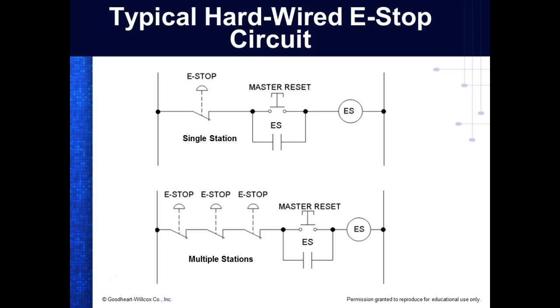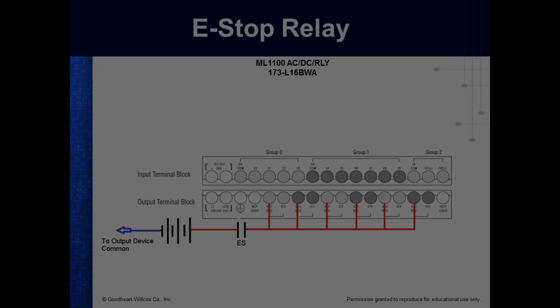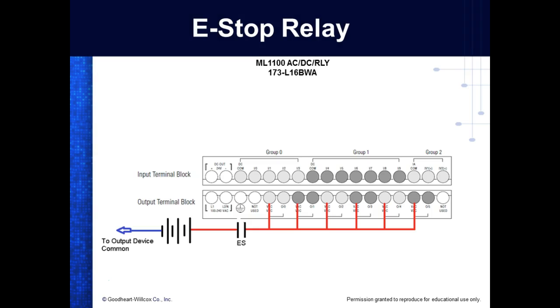Well, usually lines are divided into sections. Each section has a function in that line, and usually every section would have an e-stop button or an e-stop cord. A lot of these big production lines have cords hanging from the roof that you have to do what? You have to pull. So this is the standard e-stop circuit right here for the 1100. So here we've got these things hooked up as sourcing, right? You understand? So this is the Allen Bradley, the 1100.